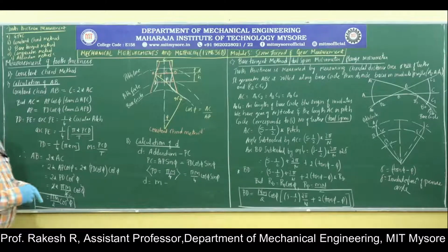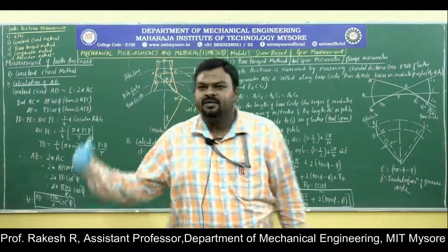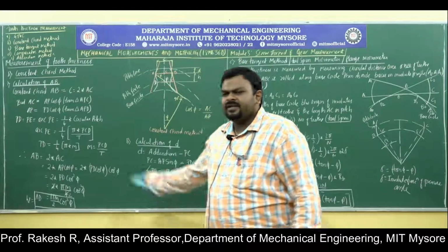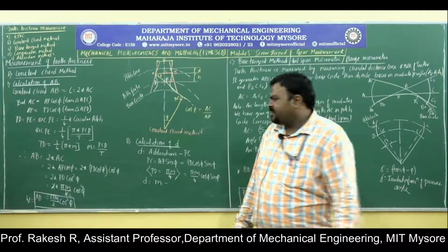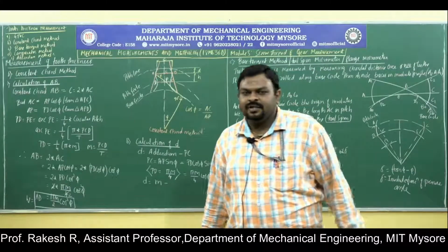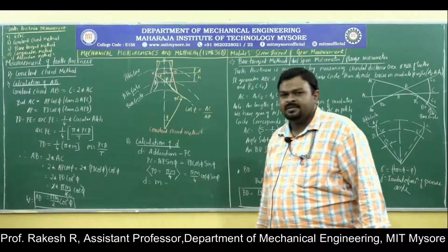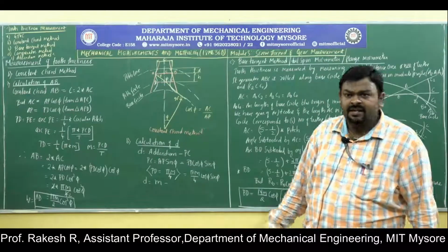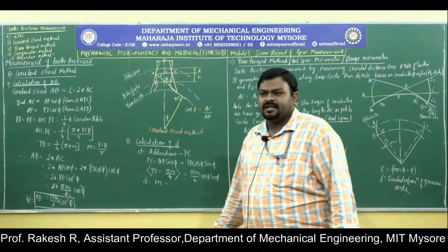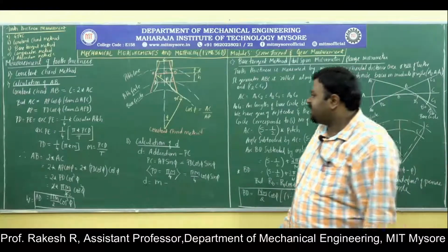So this is an expression for width of gear teeth using constant chord method. Here the parameter dependency is less. It will depend upon the module. Module is easily calculated. It is for cumulative teeth and it does not depend upon number of teeth like that. So it is easy and it is accurate compared to gear tooth vernier calipers.